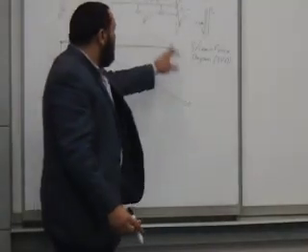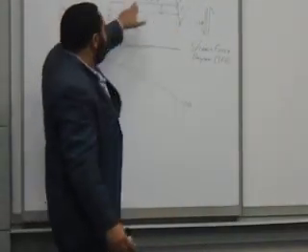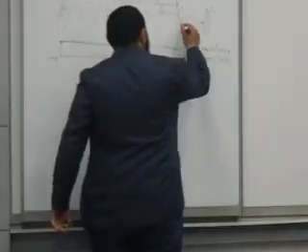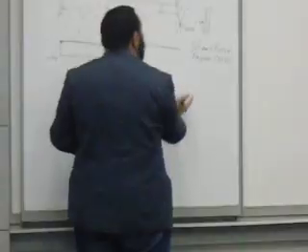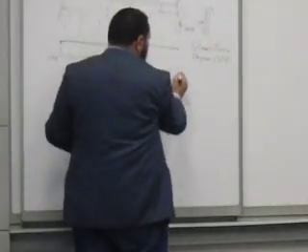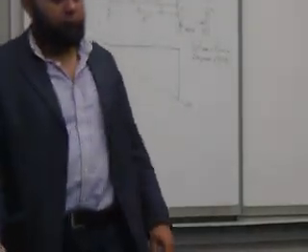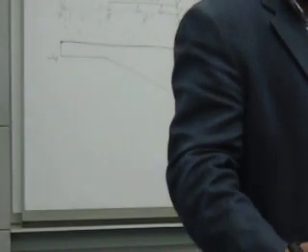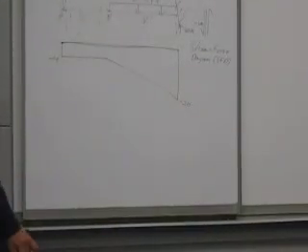So what happens here? Actually, if you go and calculate the reaction, the reaction is equal to 4 plus 2 times 8, which is 20. So 20 came up. Here after C it's receiving the reaction and this thing is closing. Making sense? Because if you take a cut after C and look right, there is nothing, there is a 0, so it must go back to 0. It must close again. Right. So you understand this.